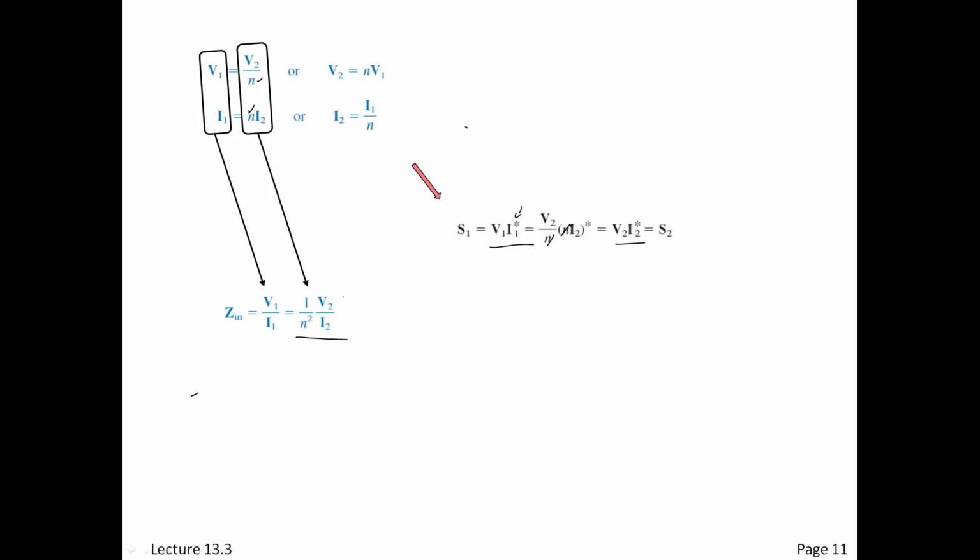So what happens here is what you might call some output impedance, right? And it reflects in as 1 over N squared, right? A little more powerful. So the output, or the load, any load attached comes across, when we had that in the picture on the previous slide, as over N squared.